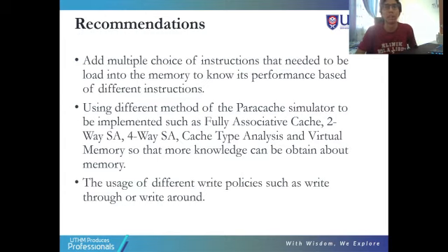There are other methods such as fully associative cache, two-way SA, four-way SA, cache type analysis, and virtual memory, so that more knowledge can be obtained about the memory. And lastly, the usage of different write policies such as write through or write around. We are using write back for our project.